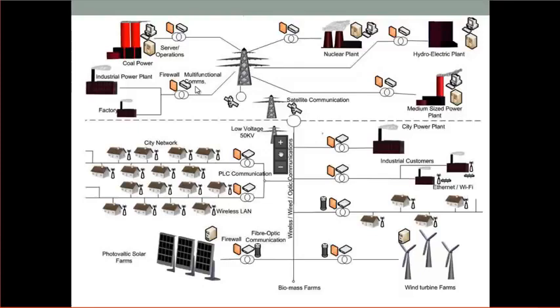They can make a pretty accurate estimation of what the load profile is going to look like tomorrow, so they can load up all their generation assets, and they know to start up the coal plant and which power plants they need to run, and how many megawatts. Maybe the medium-sized power plant over here is running at 100 megawatts in the morning, and then you tell it, by the afternoon I'm going to need you to be making 400 megawatts. But it's all very deterministic, right?